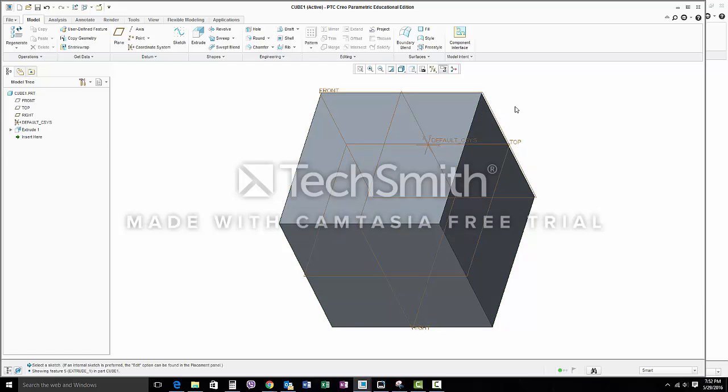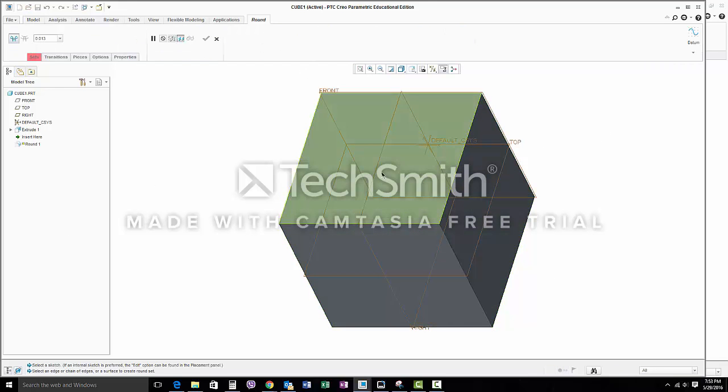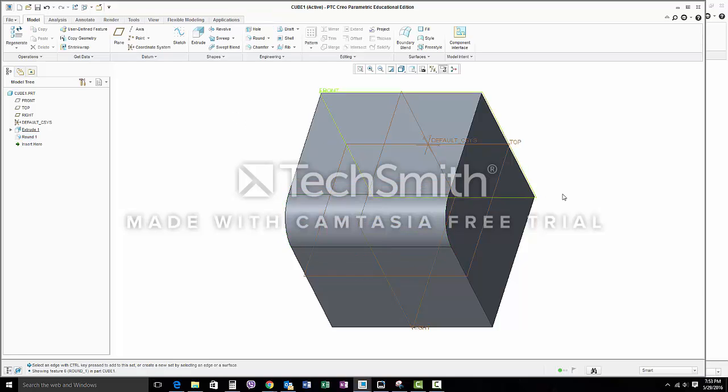Any extrusions or operations that you make will show up in the sidebar over here. So Extrude 1 would be the cube that I just did. If you want to delete or change it, or right click many operations to do that, you just click on the extrude that you just did in the sidebar and it will highlight in green for you. Another thing that you can do is round a corner: drag the white square to make the round bigger or smaller, and check mark that.